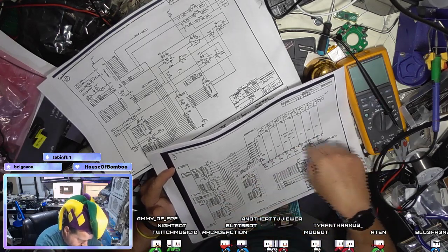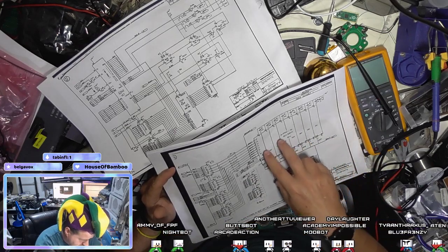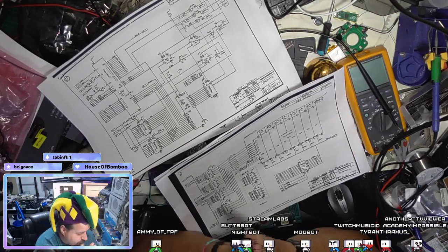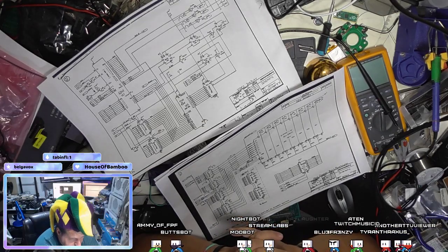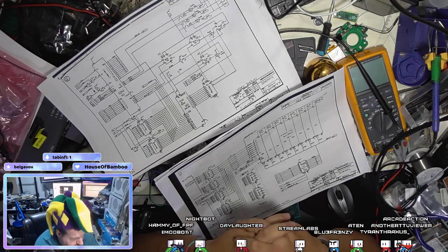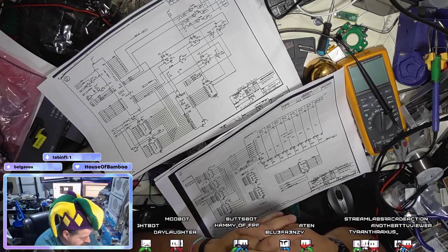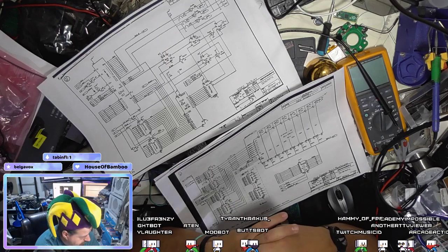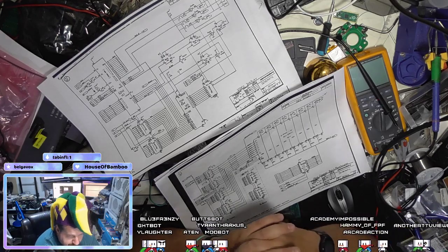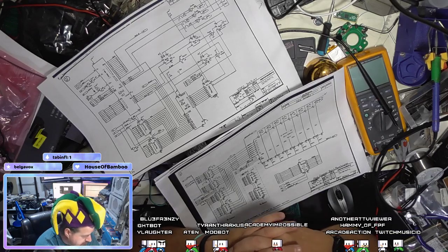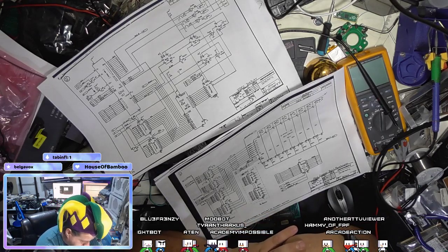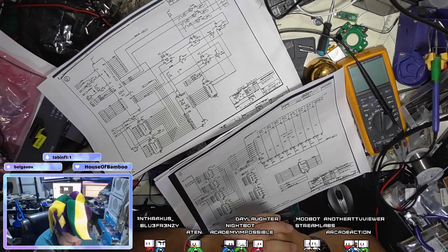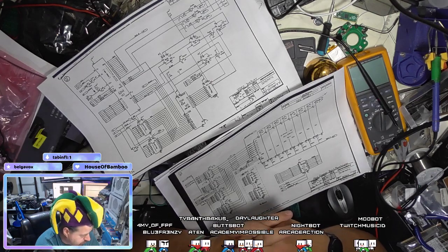So the 64K DRAM is multiplexed. The 8296 was the first Commodore where the CPU and the video controller both had access to the same RAM. So during VSync, the video controller chip would read the RAM, and then outside of VSync, the CPU would update the video RAM, and then on the next sync, the video controller would read the RAM.